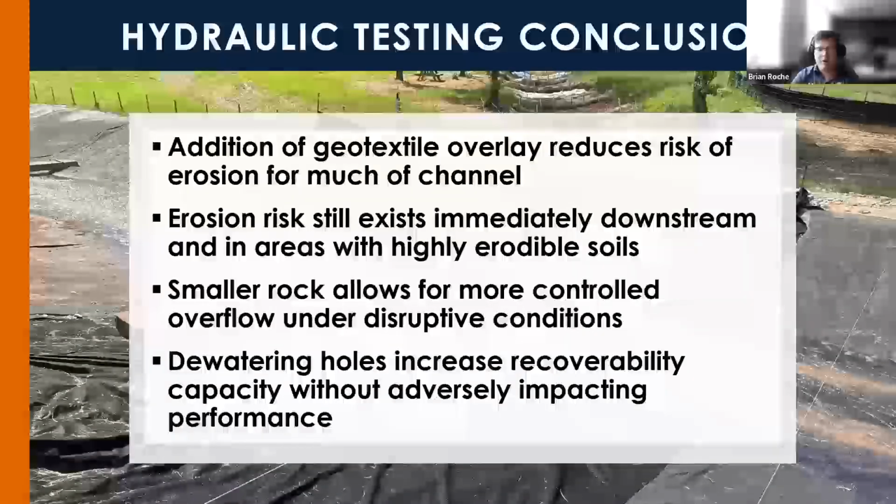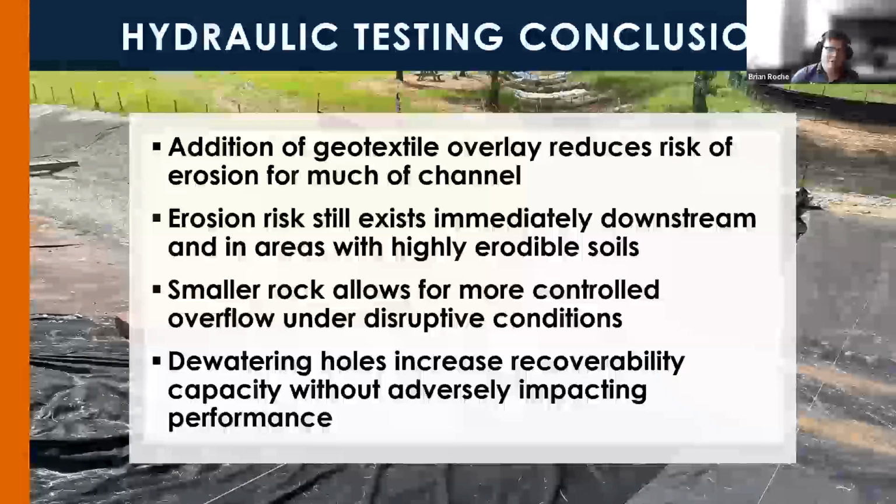With the geotextile overlay without dewatering holes, we saw extensive dewatering times. So we added dewatering holes in that geotextile overlay to increase recoverability capacity. We also found that did not adversely impact performance at all.